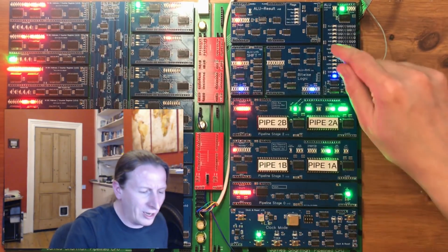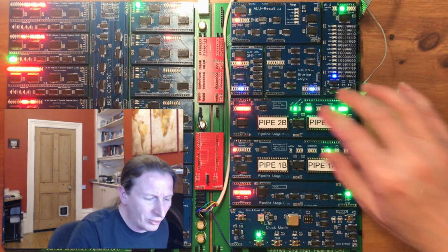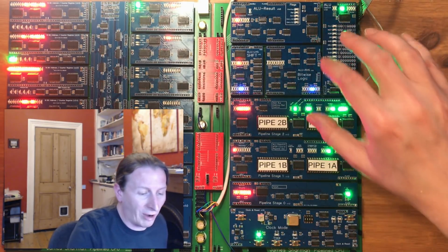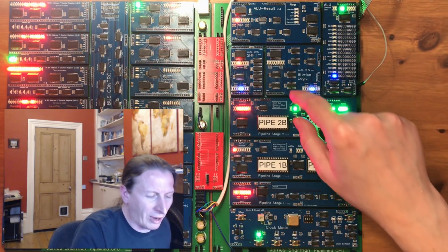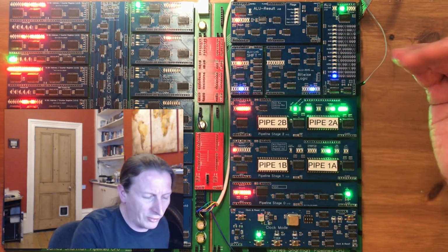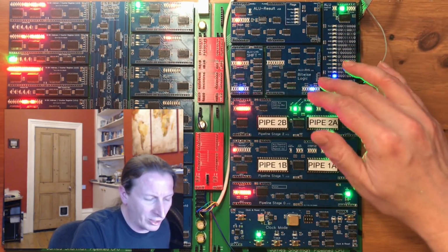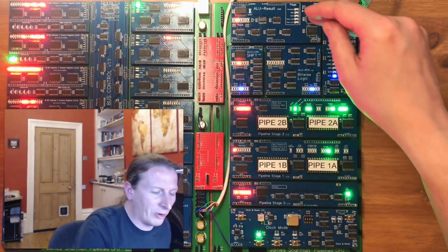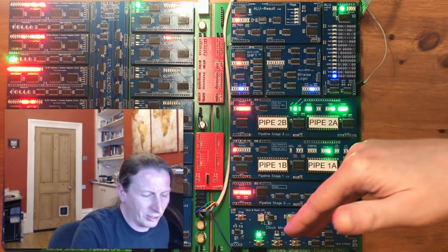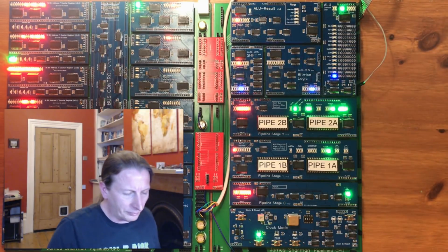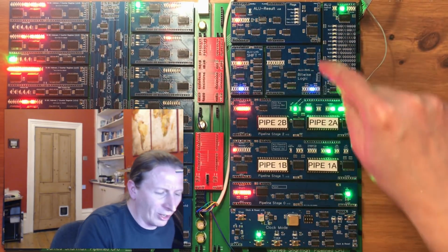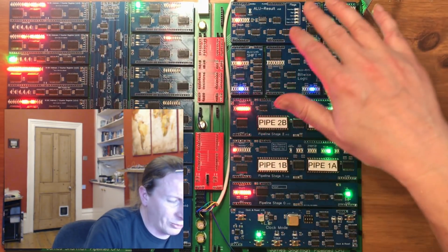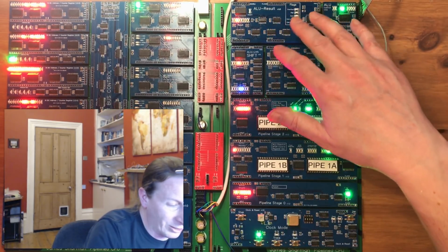Firstly, in the ALU, there's an interesting complexity in that I have separate arithmetic and logical carry flags. The logical carry is used in shifting, so when you shift a bit off the top and onto the bottom of a register, or vice versa, that's where the intermediate bit of data is stored, whereas the arithmetic carry is used when you're performing addition and subtraction. The reason I separated those is because the shift unit happens in a different cycle from the addition and subtraction in the result module.